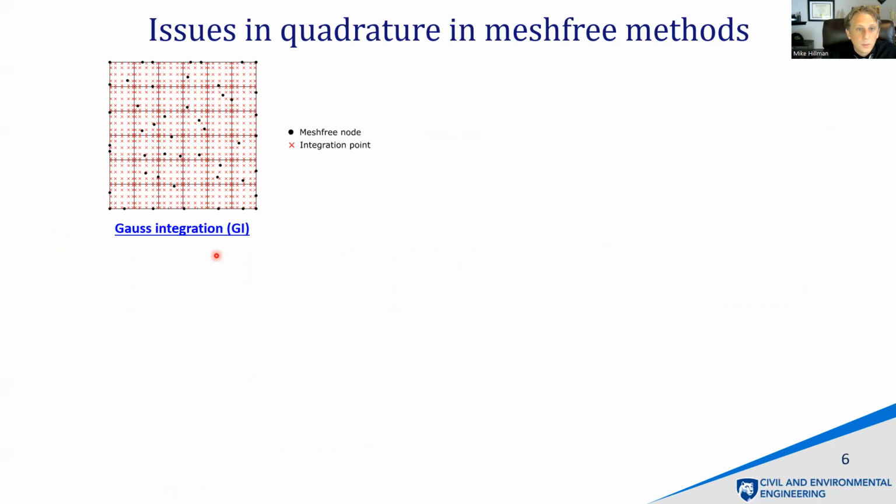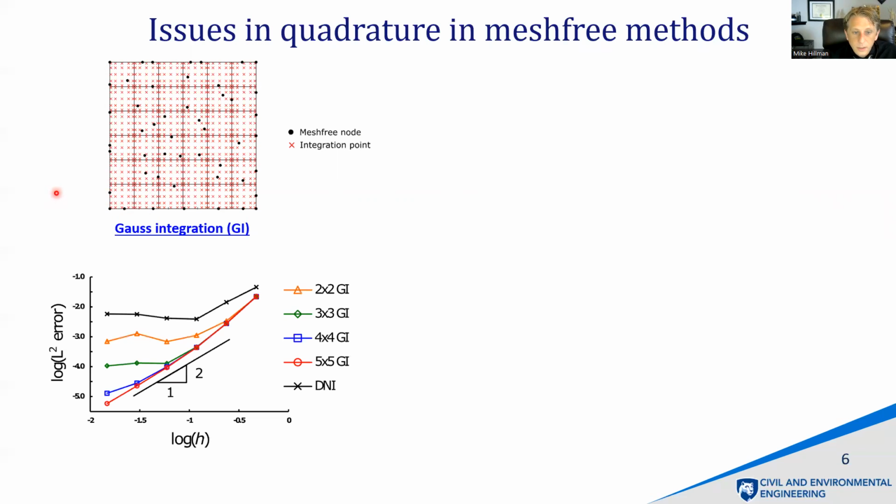And when we deal with numerical integration, let's just take something very simple, straightforward approach and just use Gauss integration. So this is called a background mesh. We're just going to construct this mesh to carry out the numerical integration and do Gauss quadrature. Okay, so these don't have to be associated with the nodes. That's another detail I won't go into much. In any case, this is just a demonstration.